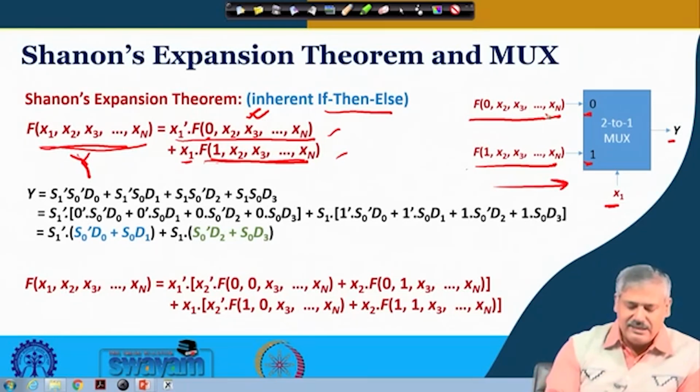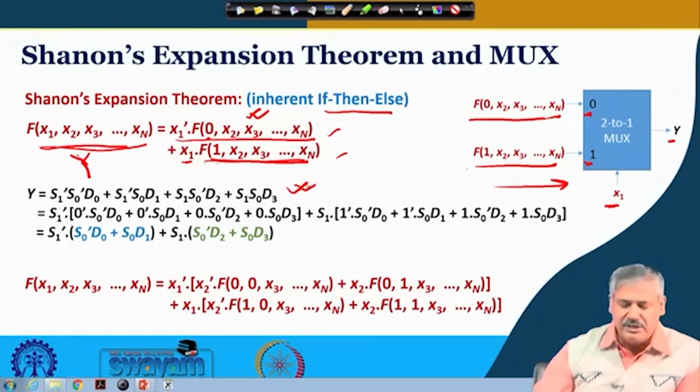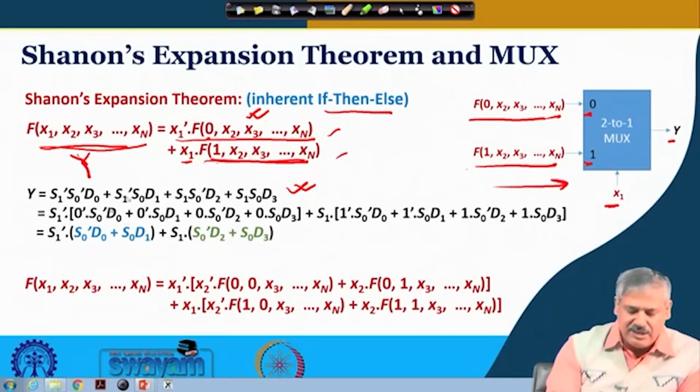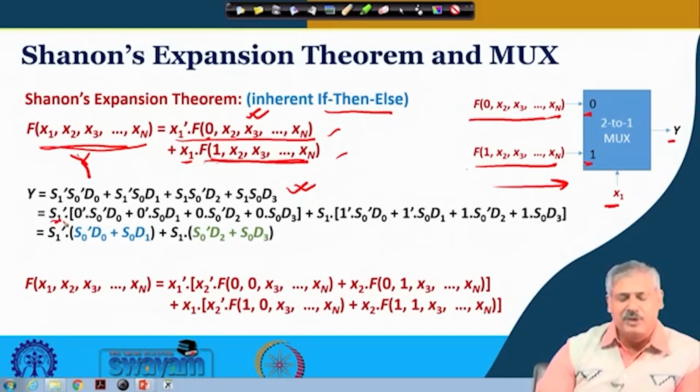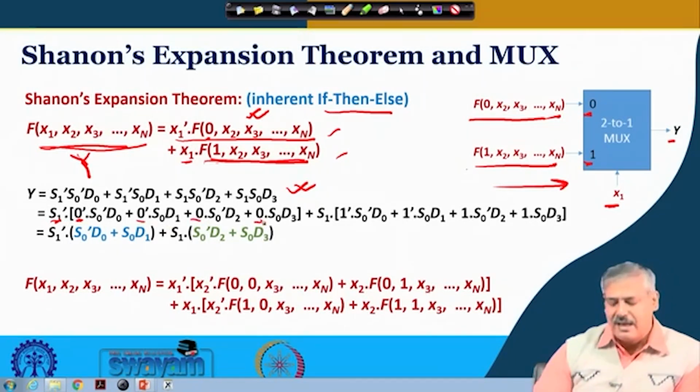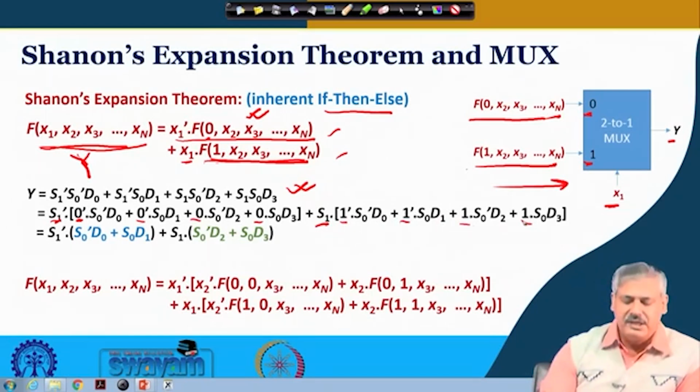And this we can put into the basic multiplexer, say the 4 to 1 multiplexer equation, and for S1 taken out as x1, wherever S1 is appearing we can put 0, 0, 0, 0, and for the other one, S1 prime, wherever S1 is there we put 1, 1, 1, 1, and then we simplify.